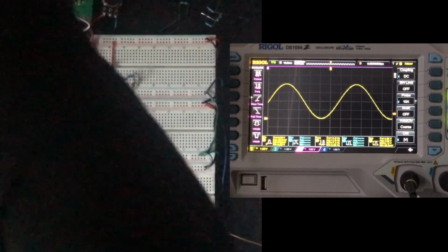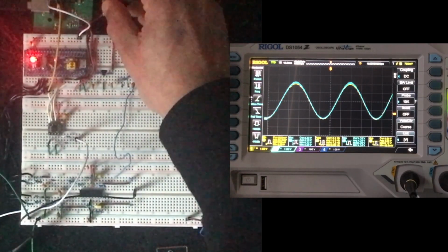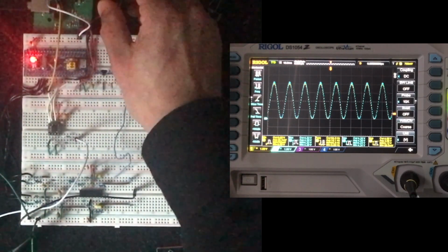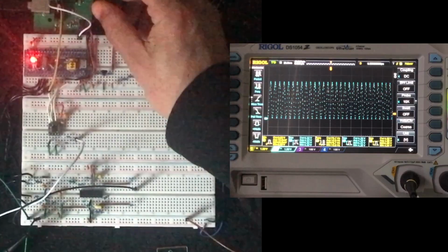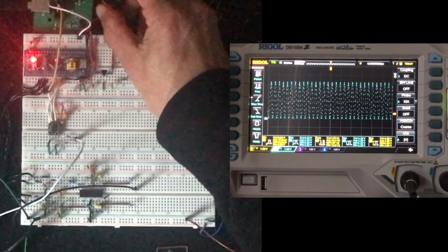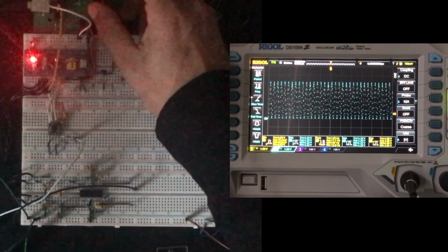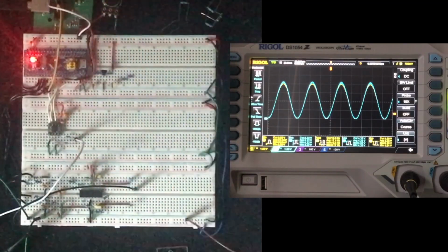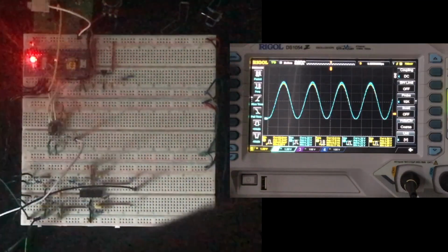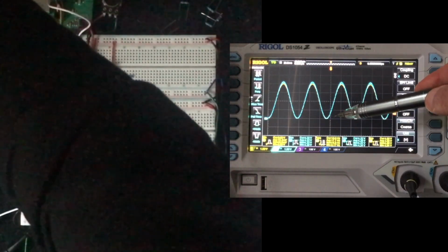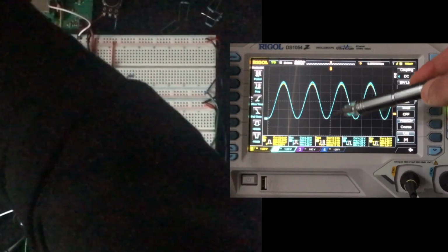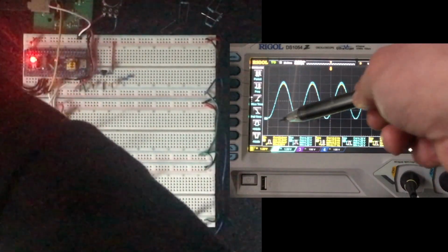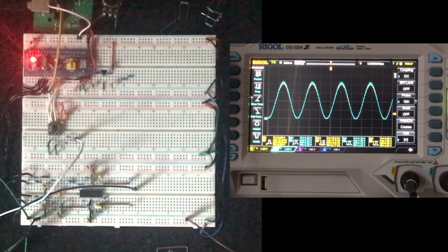Let's change some frequencies and see. You'll notice that as I increase the frequency, the graph starts to look a little bit more pixelated. So let me clarify this a little bit. When we increase the frequency over here, you see a lot more stepping. And there's a reason for this. Let's assume that this is a 1 hertz cycle. And the 12 bits, that's the resolution that interprets the values, say, vertically, right? Now the values horizontally, that's the sample rate.